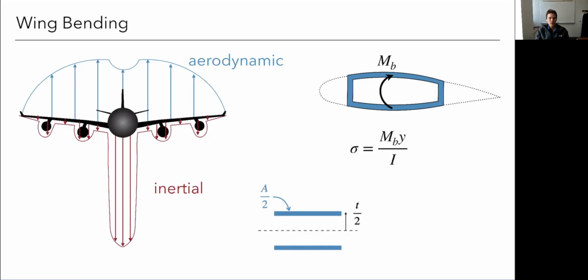And now we want to look at what is the mass of the structure that we need, okay? The mass of the structure, we could integrate. It's going to be this area, and there's half the area up top, half the bottom. We're going to integrate that area. It can be different at every airfoil section along the wing. So we integrate that area. If I didn't have density, this integral would just be a volume. So we're going to multiply by the density of the material, which potentially could change as well as it's under the integral. This is the mass of material I need.